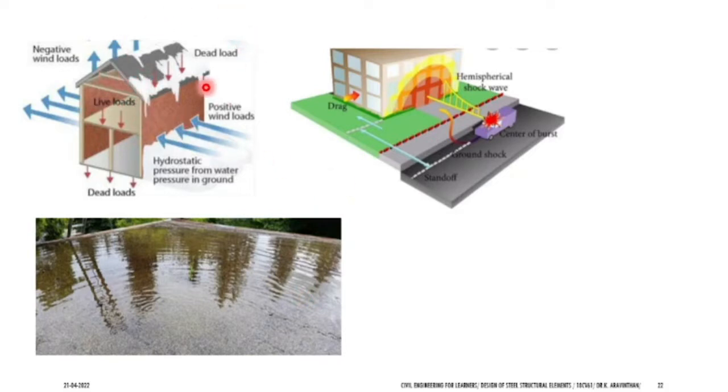Your structure, see, this is an example. For the ground floor and first floor you have to take live load, and for the second floor, do you take live load or roof load? Roof load only, so there is no live load here. Since this is a tapered one, with a tapering of more than 10 degrees, do you take the roof load as 1.5 or 0.75? 0.75, yes. So you can reduce that load according to the angle of the roof.